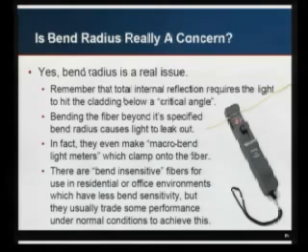So they make bend-insensitive fiber for residential, office use, things like that. But the thing to keep in mind is you have to trade some kind of performance for that. You give up low attenuation or something. So you don't really see that in the data center. So if you take your fiber in the data center and you bend it, yeah, you can look on your light meter, you can see the signal go down as you do that.